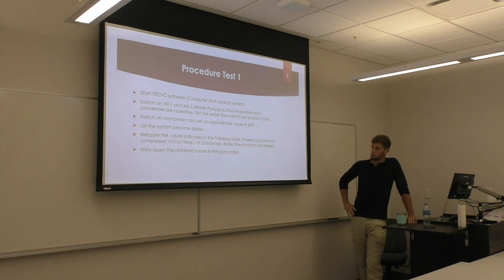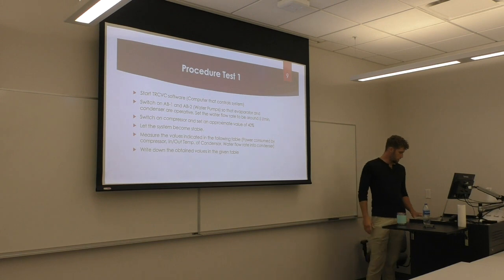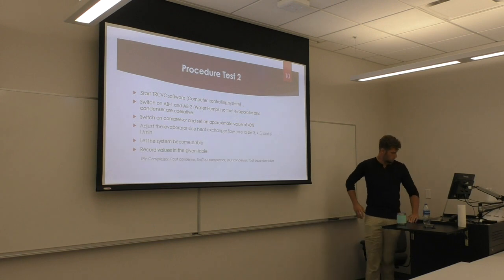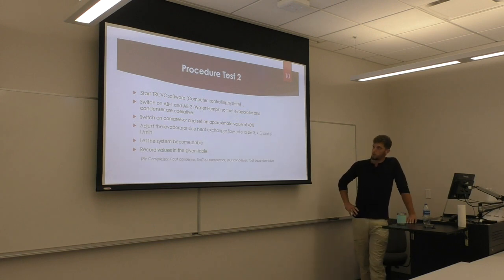The values we want are going to be the power consumed by the compressor, the inlet and outlet temperature of the condenser, and the water flow rate into the condenser. Write these values down. And then after that, we're going to perform a second test.